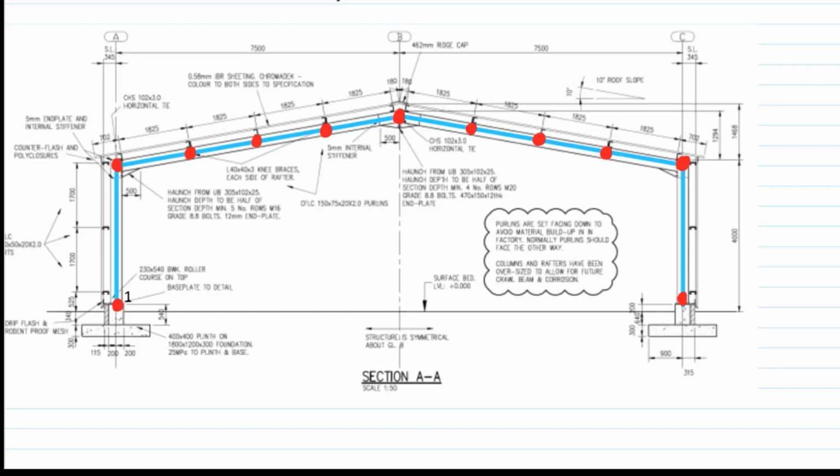And remember, your model should match the accuracy of the loads you have and also what you are designing. And remember, in steel design, the loads are somewhat uncertain, especially wind loads, and also the beam sizes we're working with are often 20% different from one to another. So either you're with a 305, 102.25, or the next size up or the next size down, and so that would be a 20% difference easily in size. So a 0.5 or 1% different in your answer is not really going to make a huge difference, but you should be accurate as possible, but also realizing that this is not perfect.